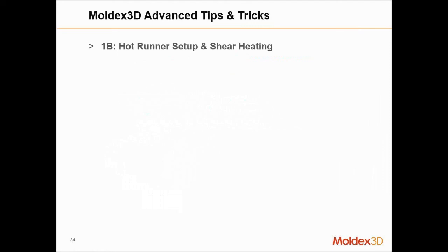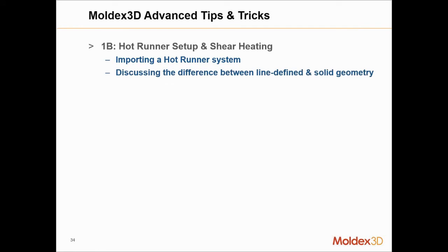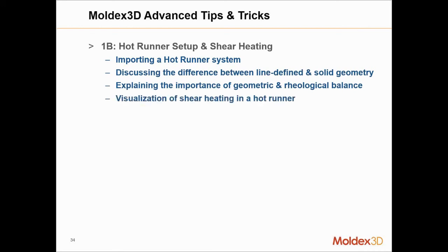Some subtopics you can look forward to are importing a hot runner system, discussing the difference between line-defined and solid geometry in Moldex3D as far as the runners are concerned, explaining the importance of geometric and rheological balance through the runner system, and visualization of the shear heating in a hot runner system after the simulation has been run.